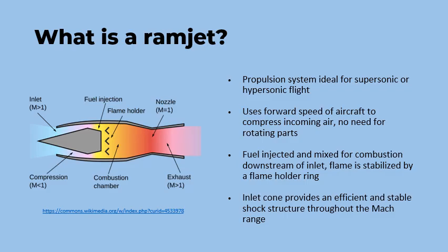So, what is a ramjet? A ramjet is a propulsion system ideal for supersonic or hypersonic flight. It utilizes the forward speed of the aircraft to compress incoming air, eliminating the need for any rotating parts.